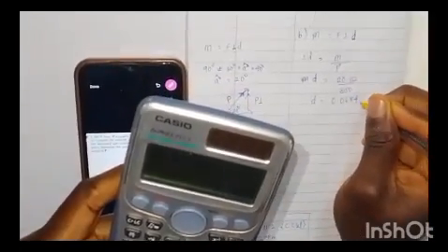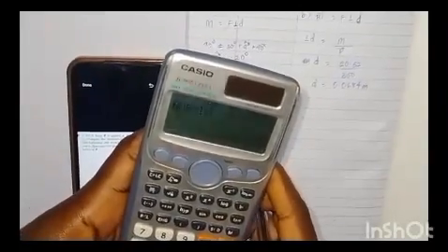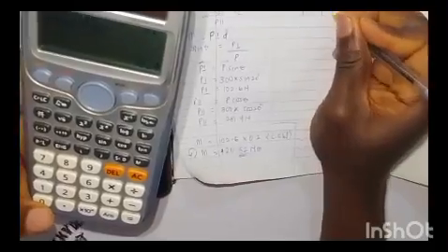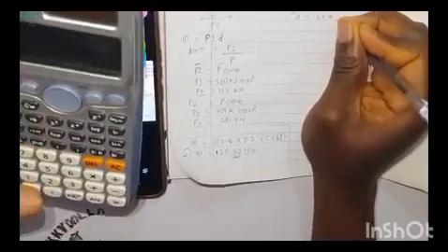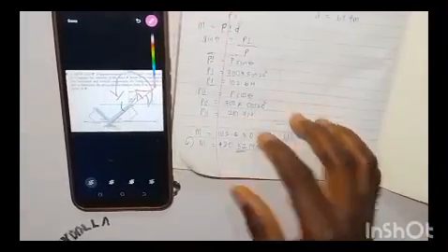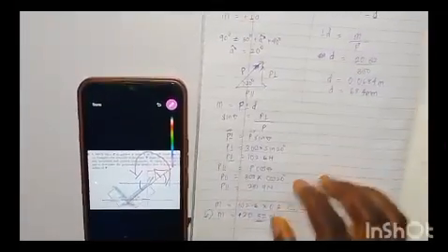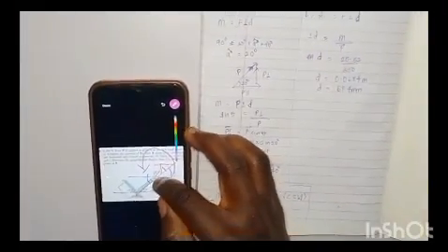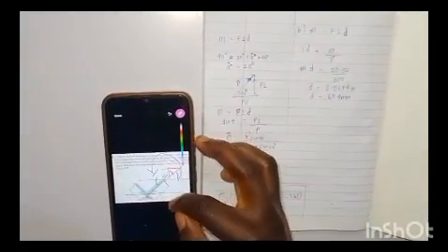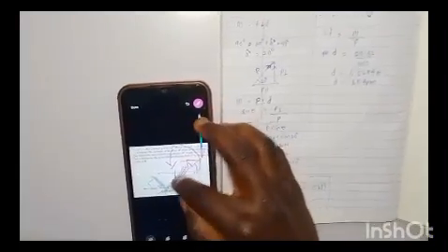which should give D equal to 0.0684 meter. So we convert this back to millimeter, that's times 1000. So your D is the same thing as 68.4 millimeter. So this 68.4 millimeter will be the distance that is perpendicular to this force, in this particular direction. As you can see, it will be in this direction.